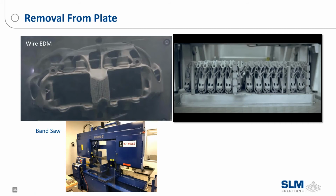So HIPping processes are almost 100% required in any aerospace spec. It's a catch-all, a fail-safe. If there's any type of void inside of the part that's produced, a hot isostatic press will more often than not close up any of those voids and allow it to be a fully dense material and to meet specification.